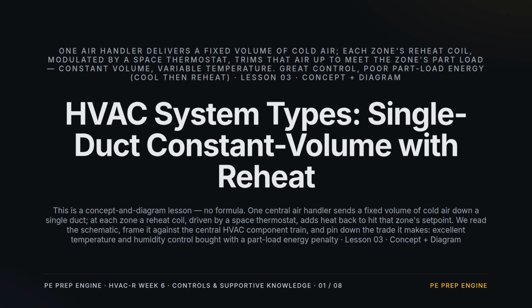Week 6, Lesson 3, HVAC System Types, starting with the single duct constant volume system with reheat. This one is concept and diagram, no formula. One central air handler pushes a fixed volume of cold air down a single duct, and at each zone a reheat coil, driven by a space thermostat, adds heat back to hit that zone's set point. We'll read the schematic, frame it against the central component train, and pin down the trade it makes. Excellent temperature and humidity control, bought with a part load energy penalty.